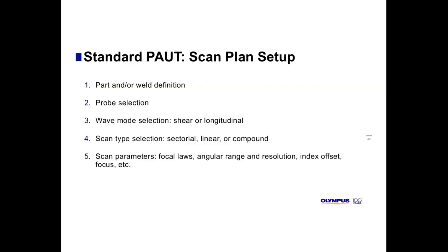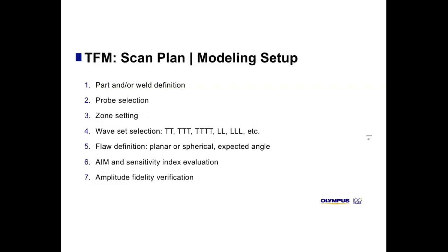Resolution, index offset, etc. Sometimes, after making this scan plan, you see that you are not covering your weld or your part in the right way, so you will decide to change the probe maybe. Now, let's see the scan plan in TFM. And here I'm introducing a new concept, which is the modeling.